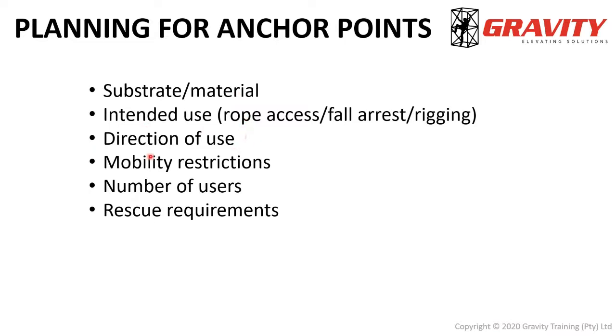Then we have to consider the direction of use. We will talk about that in more detail in a second as well. The direction of use of anchor points is extremely important, because some of these anchor points have been designed and manufactured with a given direction in mind, having a certain direction of an axis of force which is stronger than the other axis. I'll get to that in a later slide as well. So remember, if you want to use an anchor in a certain direction, consider that before you start placing anchors and using anchors.